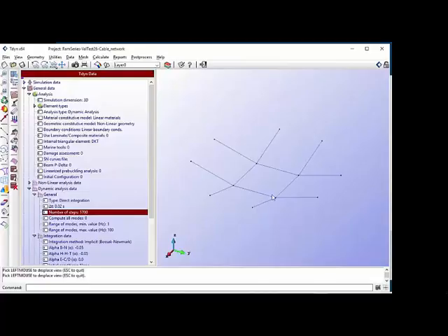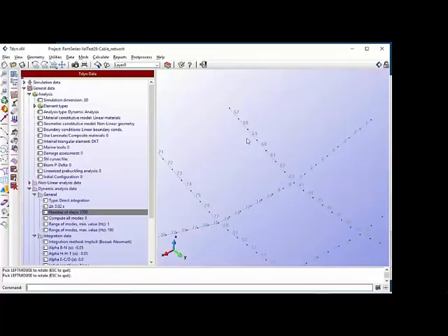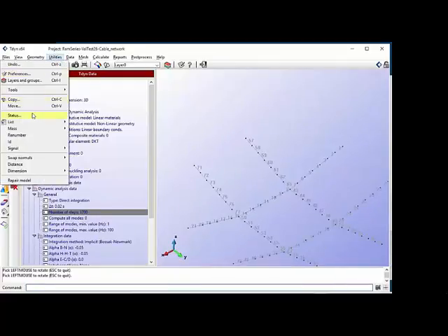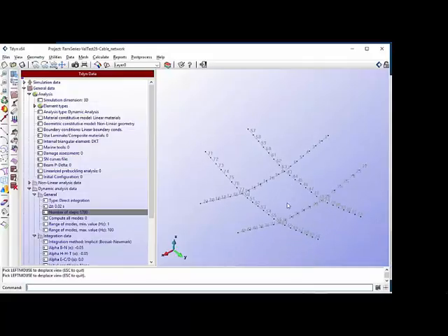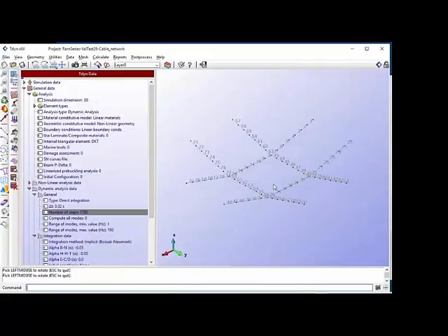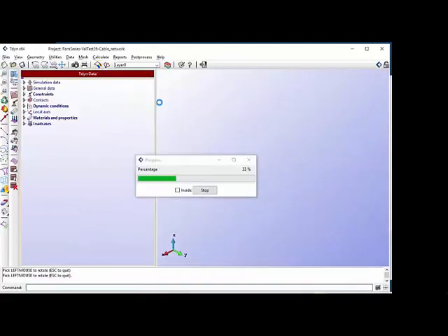And regarding the mesh, it's also a very simple mesh. It's just about 84 nodes and 84 elements. We can also label them. I can show you the elements and the nodes. In this case, as I was guessing, yes, 84 elements. So it's a very simple analysis. It doesn't take much CPU or memory. So we can go directly to the post-process and visualize some results.